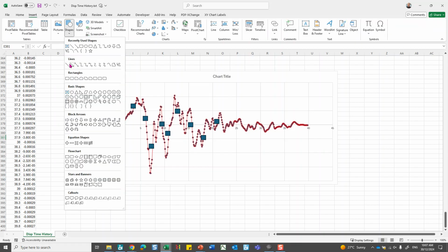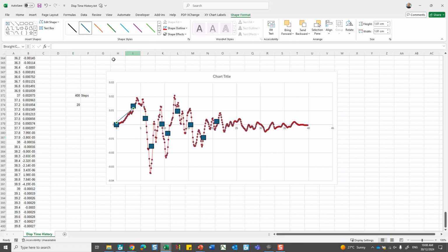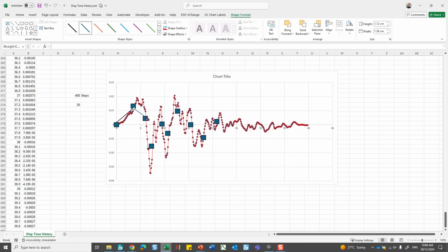So I would go to line here. PLAXIS will say, okay, I am connecting this to that. We will give it maybe a different color. So give it black, and then I will see the next one. So this is the next one. You see now how I started to deviate from my loading regime.